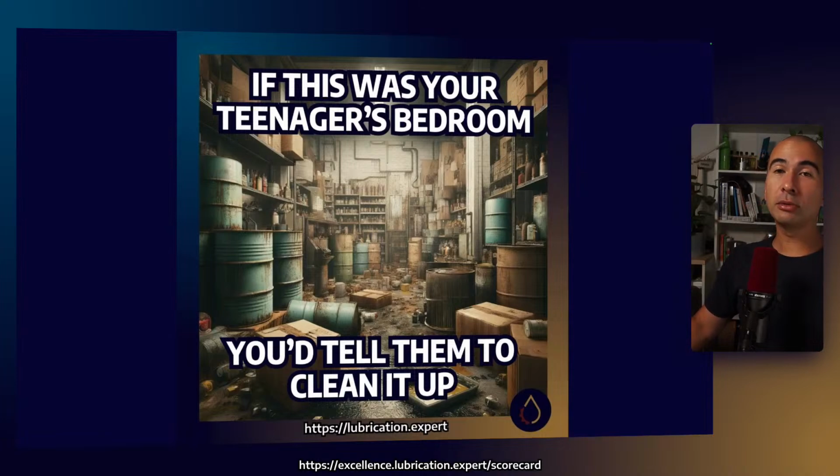In terms of storage and handling of lubricants, think of it as just good housekeeping practices. We want to make sure that our storage areas are undercover where at all possible. If it's possible to climate control them, that's great, but that's not always possible. And we want to make sure that where possible, we are rotating our stock and we are keeping everything, again, clean, cool, and dry.